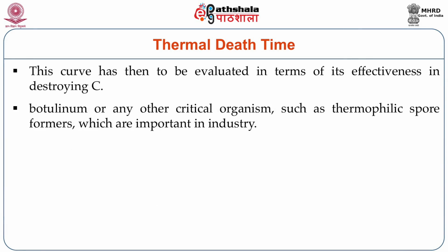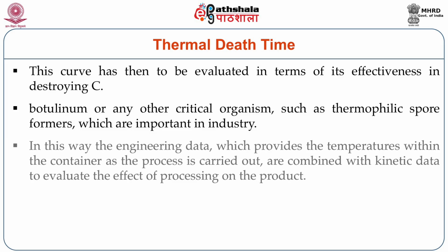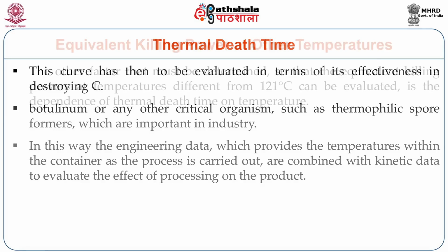This curve has to be evaluated in terms of its effectiveness in destroying the Clostridium botulinum or any other critical microorganisms such as thermophilic spore formers, which are important in the food industry. In this way, the engineering data, which provides the temperatures within the container as the process is carried out, are combined with kinetic data to evaluate the effect of processing on the product.